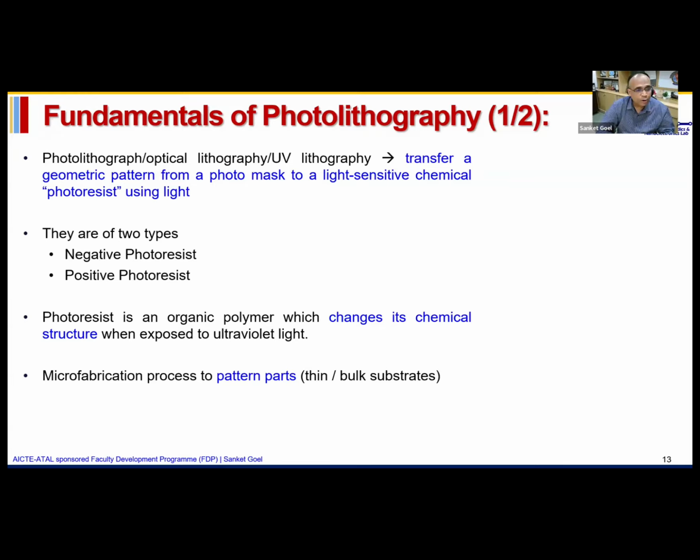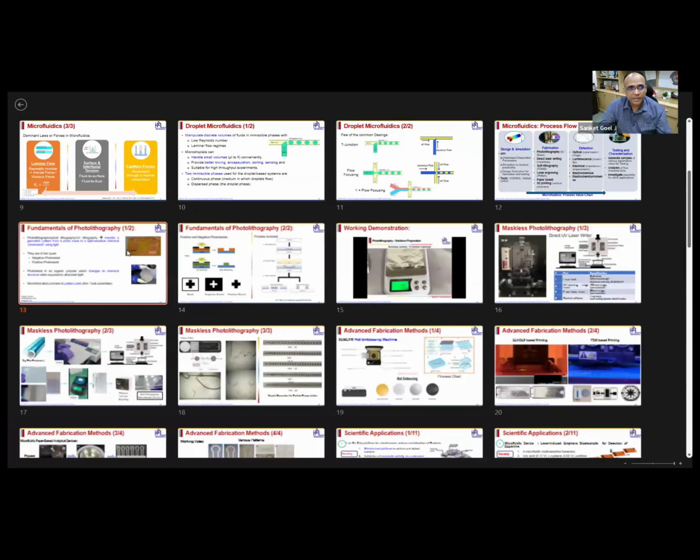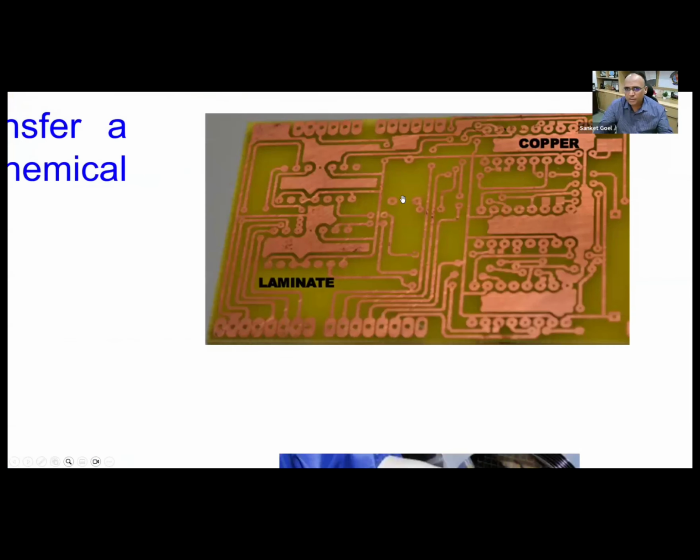And of course, the government of India is focusing a lot on semicon. So learning and developing our own understanding of photoresist is extremely important. So you can see that by using those photoresists, I can create this structure on a simple PCB. What we have done is use some of those negative photoresist films and then shine UV light and create the patterns.